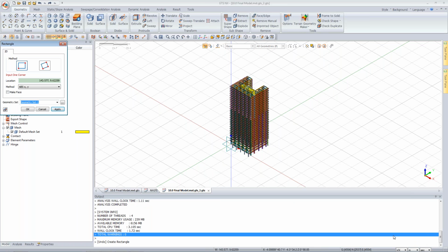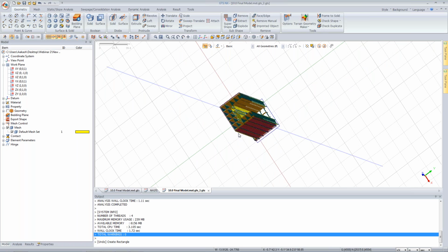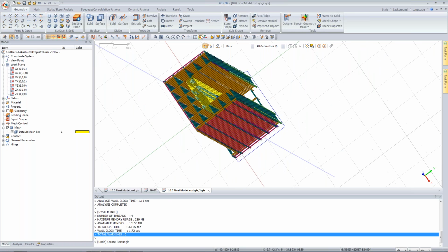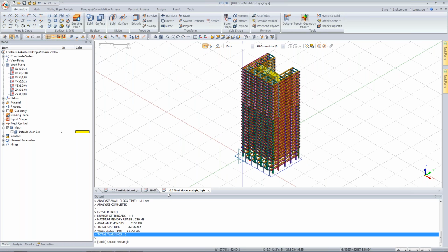Anytime you can change the unit system from the right bottom corner. So minus 5.7 comma minus 5.1, enter, and then 48 comma 40. These are the units in meter. Fine. This is just for demonstration purposes. I have just created it, you know, this couldn't be this close. I'm just taking this for a demonstration, so you can increase the size as well. Then this is basically the dimension of my raft.